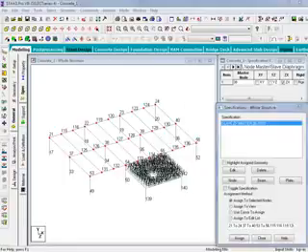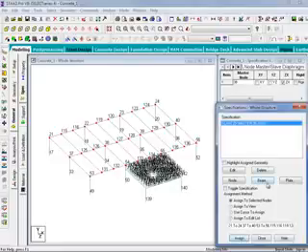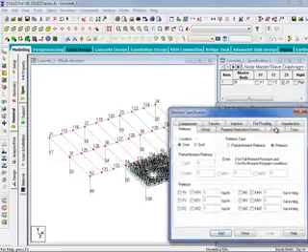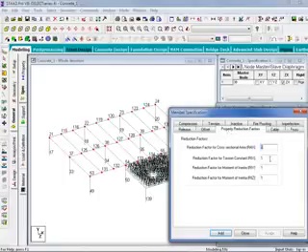For this particular model, we're also going to assign some property reduction specifications for our concrete beams and our concrete columns. To do this, we're going to return to our Specifications dialog and click on the Beam button. Here I can see all of the member specifications that I can assign to the model, and for this model I'm going to select this property reduction factors.